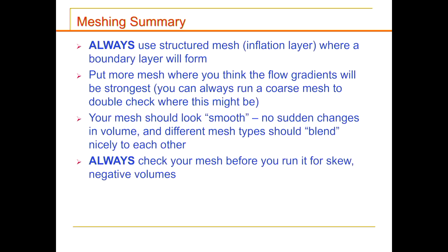Basically, this will be 1.5, again 1.5. It's got to be smooth. You can't have a mesh of this size and eventually have this mesh size. That is not smooth, because you get too much of a step change in the flow, and you will find your solution will diverge very easily. So having a smooth mesh is an important part of getting a good solution.